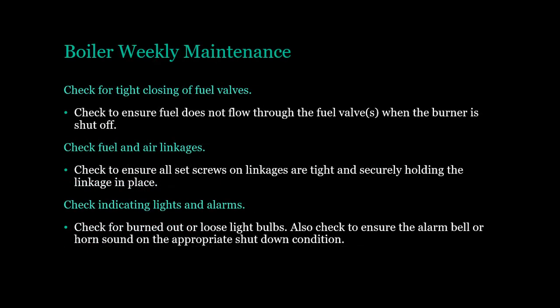Boiler weekly maintenance. Check for tight closing of fuel valves. Check to ensure fuel does not flow through the fuel valve when the burner is shut off. Check fuel and air linkages. Check to ensure all set screws on linkages are tight and securely holding the linkage in place.